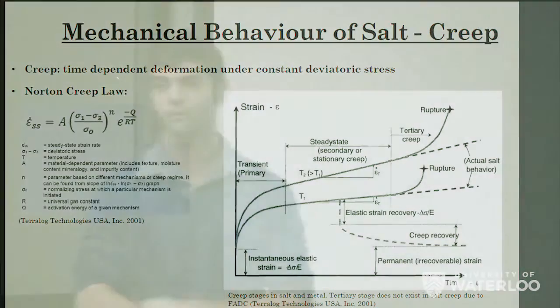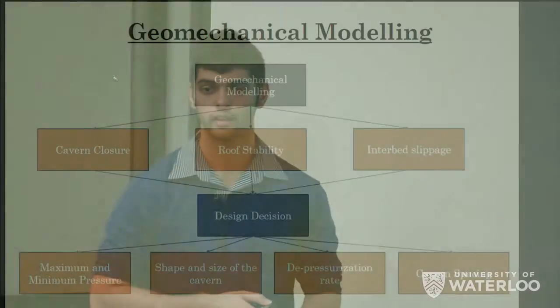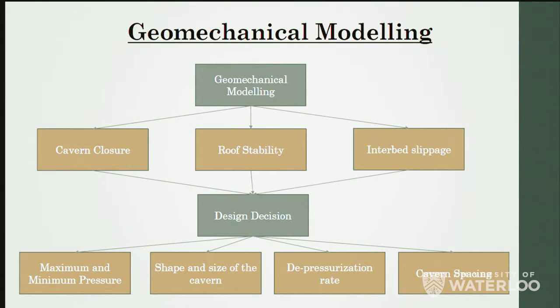So the third phase is numerical modeling of salt caverns. The objective of this phase is to make design decisions such as finalizing maximum and minimum operating pressures, finalizing the shape and size of the cavern, the depressurization rate, and finalizing cavern spacing. While doing numerical simulation, we need to consider cavern closure, roof stability, and interbed slippage.